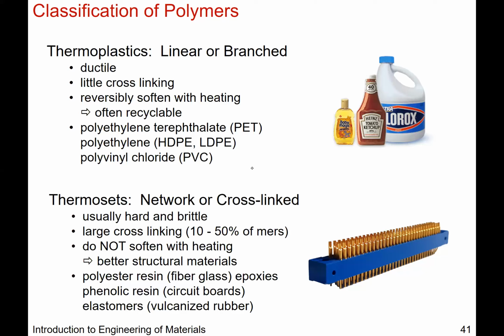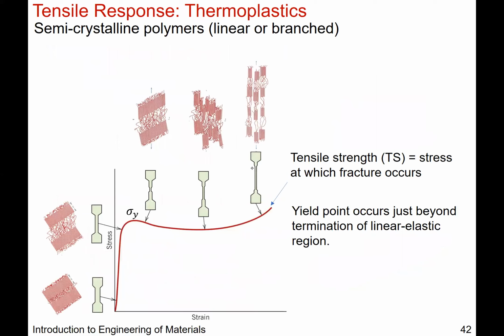Okay. In the picture that you see here, you typically see thermosets in microelectronic examples, so the blue polymer material that holds a bunch of pins together, right? You want something that's high temperature because obviously electronics can get quite hot. And so if you have these low melting point thermoplastics, your material, your device can actually degrade much more quickly. So you want thermosets as the casing, or in this case, part of to hold a bunch of pins together for some plug. Okay. So quite useful, but obviously very different type of mechanical properties.